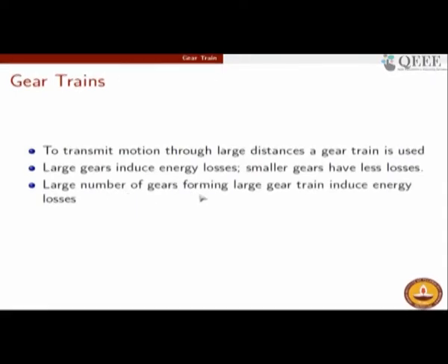So a large number of gears forming a large gear train will also induce energy losses. So one has to take care that you should not use too many gears also, because if you use too many gears, then again the load on your transmission is increasing, and you would do well to keep it under control, because that is like a parasitic energy loss in your transmission.